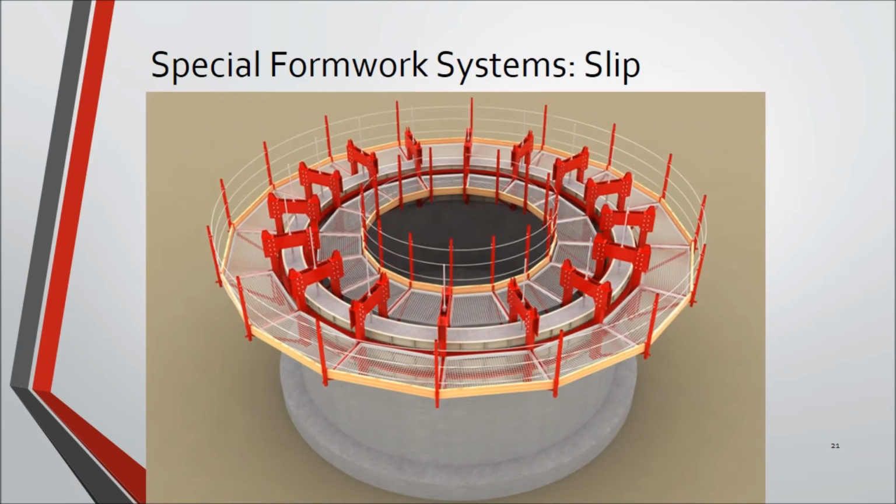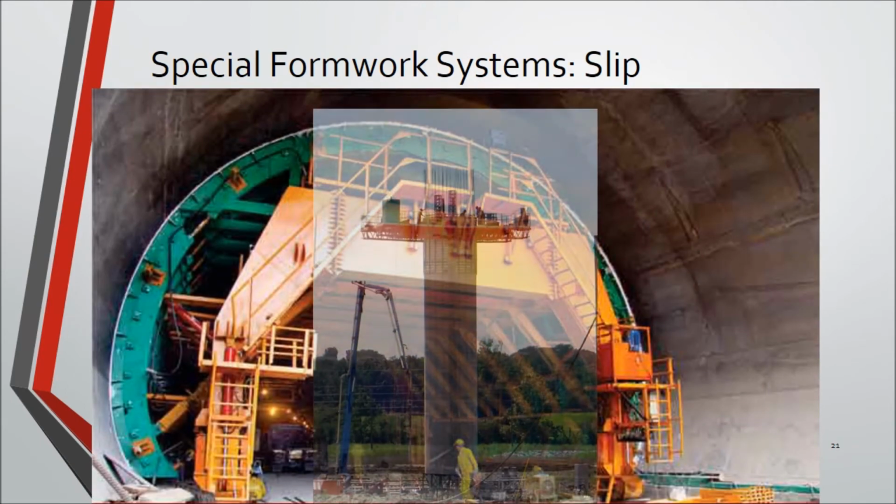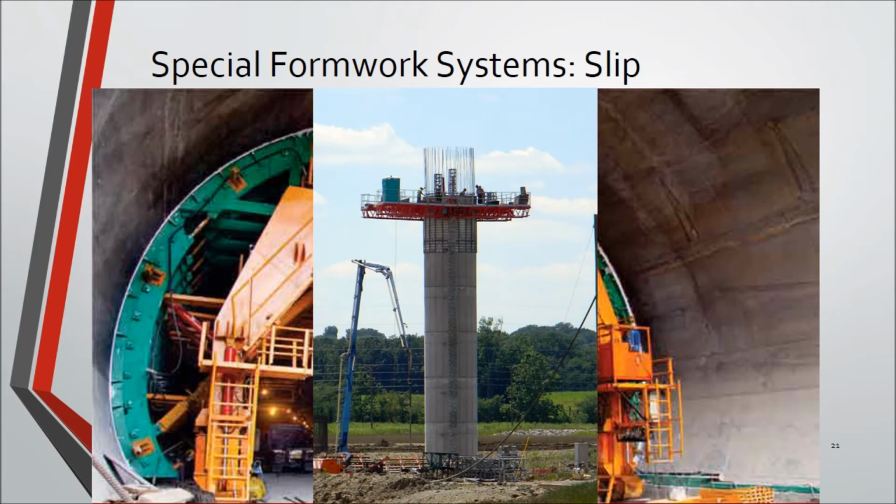Slip form means a continuously moving form, moving with such a speed that concrete, when exposed, has already achieved enough strength to support the vertical pressure from concrete still in the form, as well as to withstand lateral pressure caused by wind. The main advantage of this technique is the continuous productivity of the equipment.